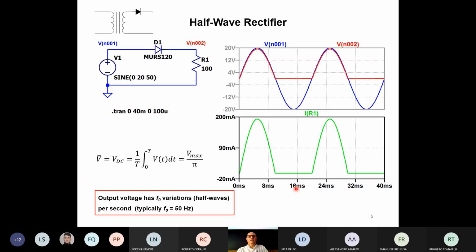So now we can see the different circuit. For doing this, I used the software LTspice, and I've done a simulation of our circuit. The top circuit is what we are considering. Just for simulation reasons, I have removed the transformer, and instead I've placed an equivalent generator, which gives the voltage coming out from the secondary of the transformer.